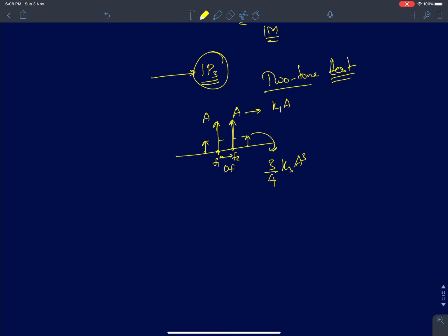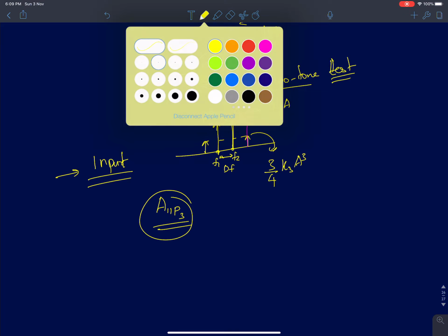Now, when I apply an input, I'll call it IIP3. This is called the input third intercept point. Input third intercept point is nothing but a way to define the nonlinearity in terms of the input amplitude you apply. When you apply this amplitude, the strength of the intermodulation terms becomes equal to the main desired signal itself. So that parameter talks about how nonlinear your system is.